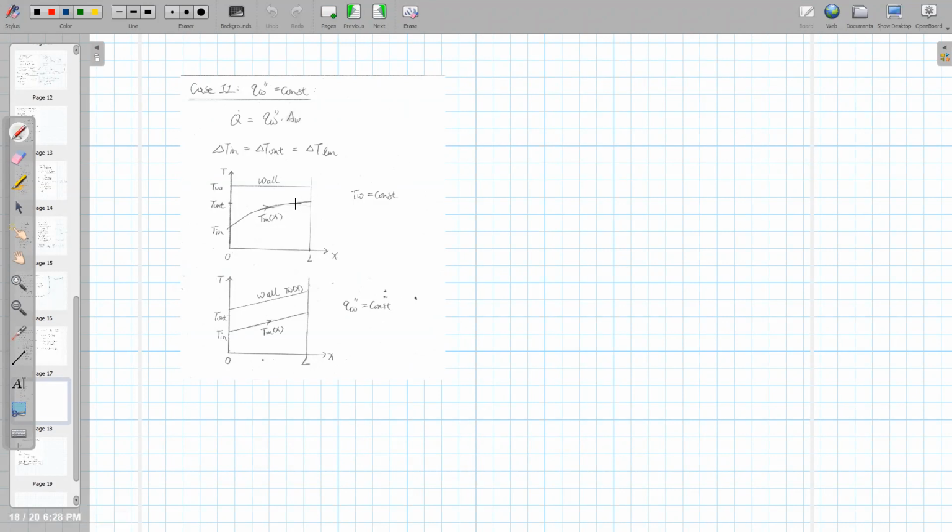You remember that our Nusselt number is defined by h d over k, right? And the q_w double prime is calculated by h times (T_wall minus T_m), okay? So this is what you know. But for these cases, your wall temperature is fixed, and your mean temperature is actually keep increasing, okay? Keep increasing even after the flow is fully developed.